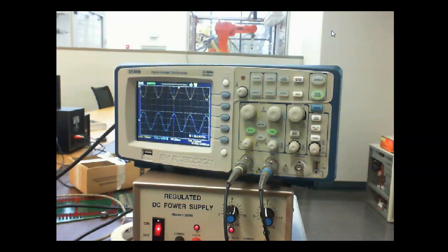A lot of people think with those stereos, if you want to add multiple speakers, you just hook them in parallel. Well, they're 2 ohm speakers. If you hook 2 in parallel, you drop down to what? 1 ohm. If you hook 3 in parallel, now you're out of impedance matching and you get distortion anyway. So you hook some of your speakers in parallel and some of them in series, to get the maximum power transfer. People don't understand that. So now you know why stereos give you awful sound, right? Either they're not hooking their speakers up right, or they're hooking them out of phase.